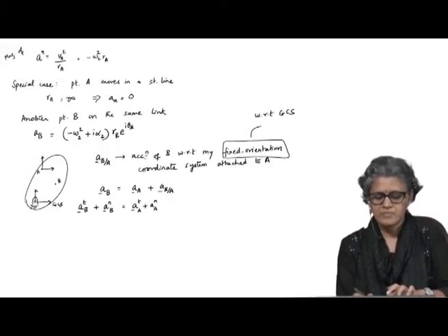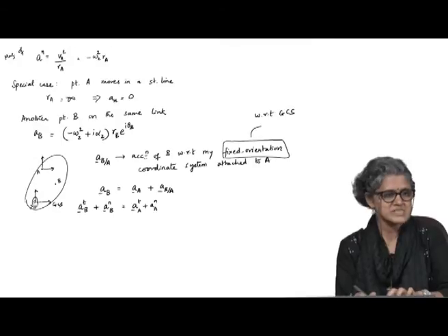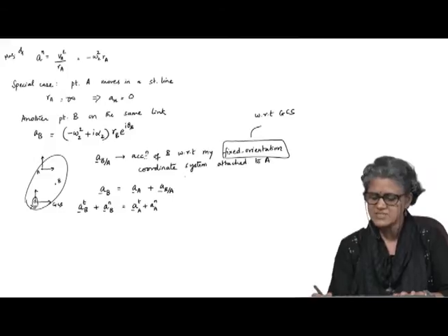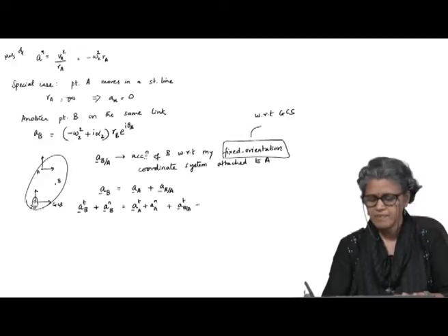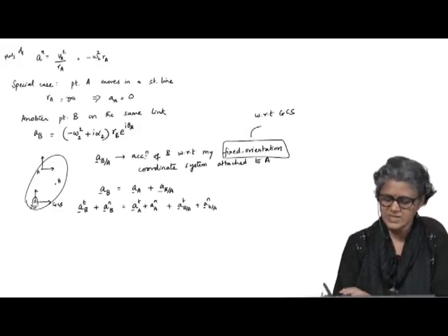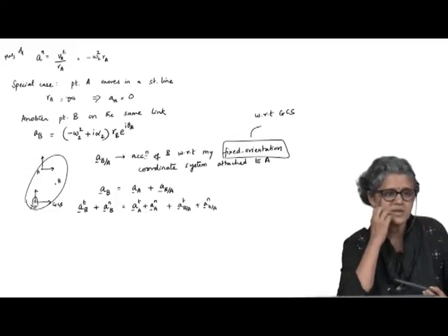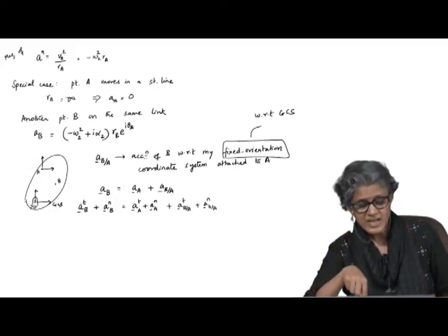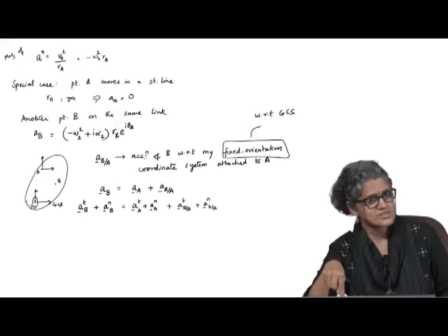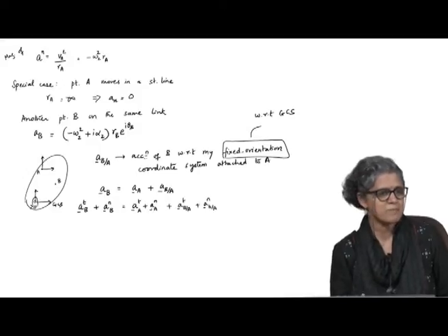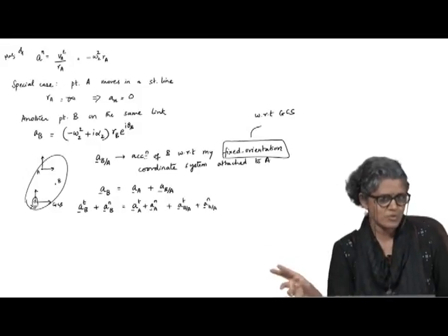Similarly, it is like my sitting at O2 and observing A; now I am sitting at A and observing B. So, this relative acceleration will also have a tangential component and a normal component. In the case of 2 points fixed on a rigid body, the tangential direction of this is not the same as the tangential direction of something else, so I can't equate all the tangential components.